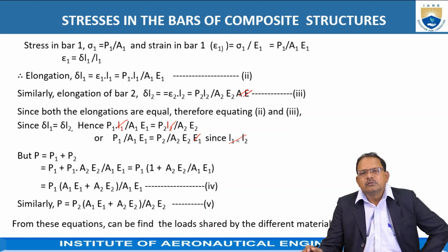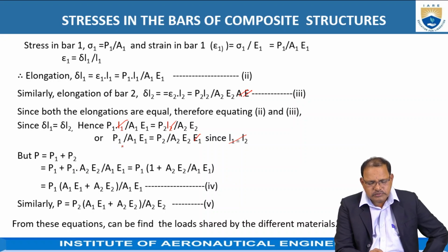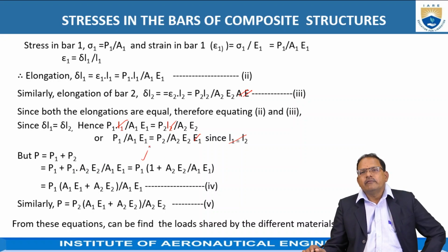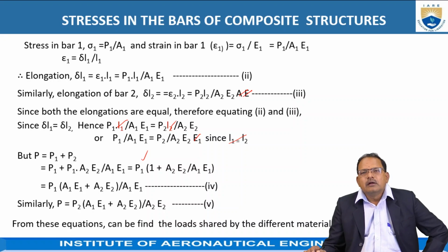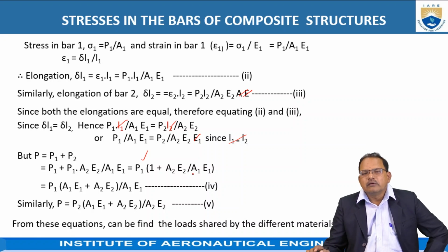But P is equal to P1 plus P2, that is the load sharing. Since P1 divided by A1 E1 is equal to P2 divided by A2 E2, P2 is equal to P1 divided by A1 E1 multiplied by A2 E2. Taking P1 common, the remaining value is 1 plus A2 E2 divided by A1 E1.